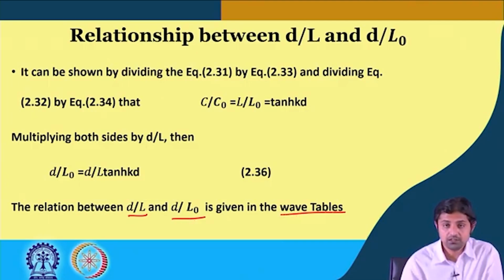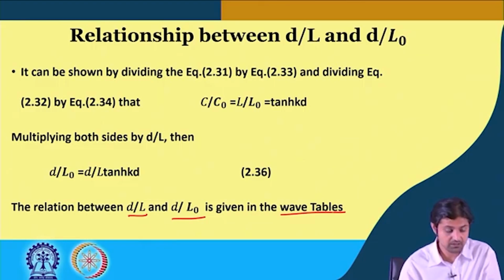So, if you want to calculate this, there is something called wave tables, which I won't show you in this course, but if you need to solve, you can always use the trial and error method for solution of the dispersion relationship. But most of the questions that you will be getting in your assignments will be based either on deep water or very simple cases, where you can use the equations like the dispersion relationship or the velocity potential.